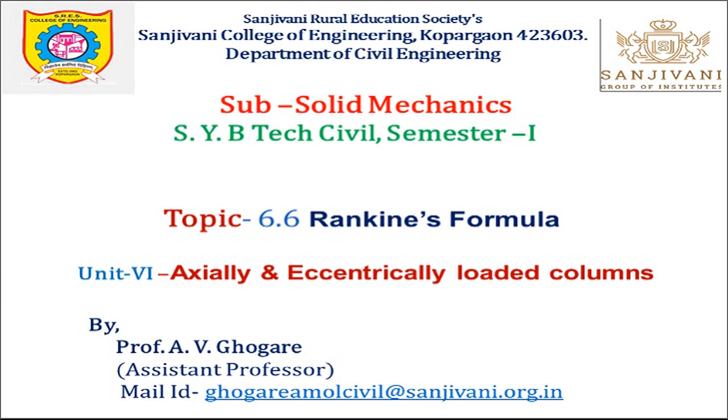In this session, we are going to study one topic in the axially loaded column and eccentrically loaded column, unit number 6. The topic is Rankine's formula. In the earlier sessions, we have studied Euler's theory, but that Euler's theory is only useful for long columns, which fail due to bending stresses or buckling stresses. So that theory we studied last time is only for long columns.